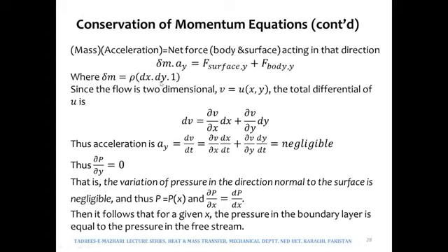So we have put the expressions for mass by writing it in the form of density times volume, the expression for acceleration, and the surface forces in x direction. Now we are going to do the same in y direction. So delta m, a small elemental mass of the differential element, times the acceleration in y direction would be equal to the surface forces in y direction and body forces in y direction.